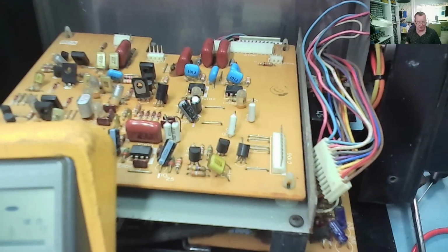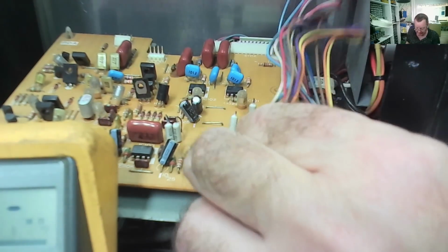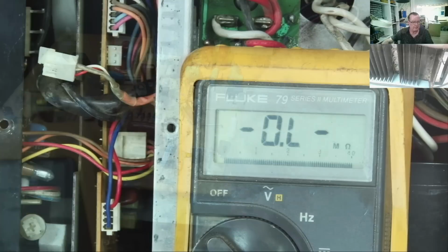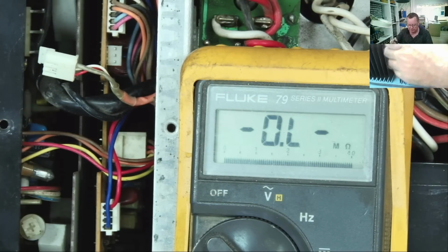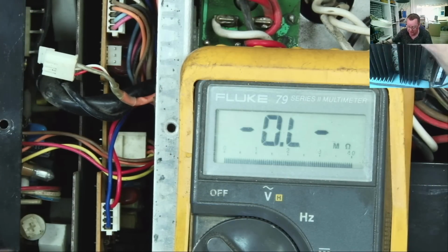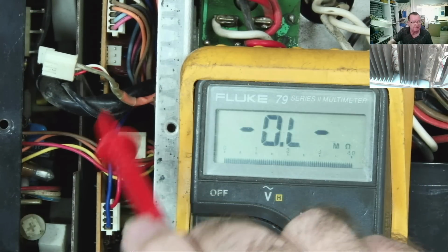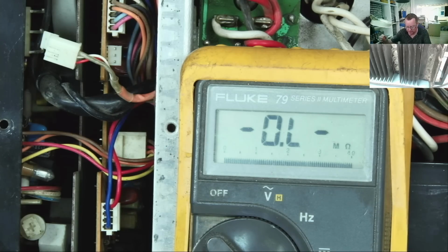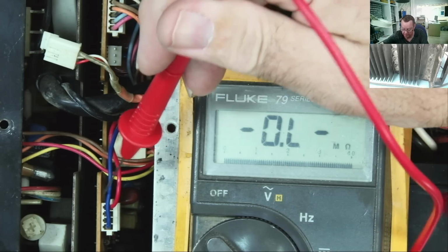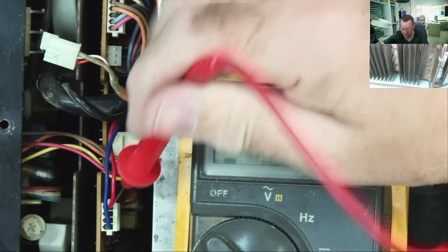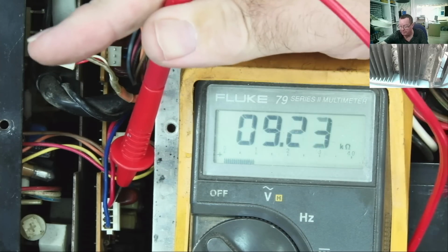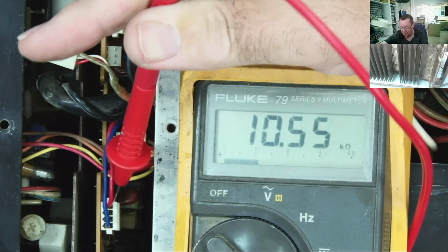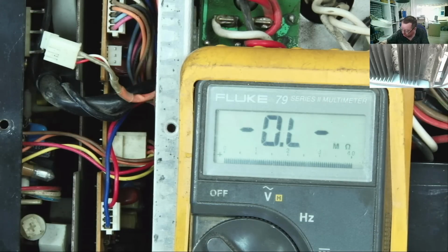So wherever this is going, this appears to have the problem. I'm going to have to get somewhere where it can work a bit better. But anyway, that low resistance is somewhere on that cable. I've put this back on pretty much now. It's held on with one bolt, but it's there. So I've disconnected that wire. Let's see what we have. Well, we have like 10 kilo ohms or more. Okay, so the short has gone. Well, low resistance has gone.